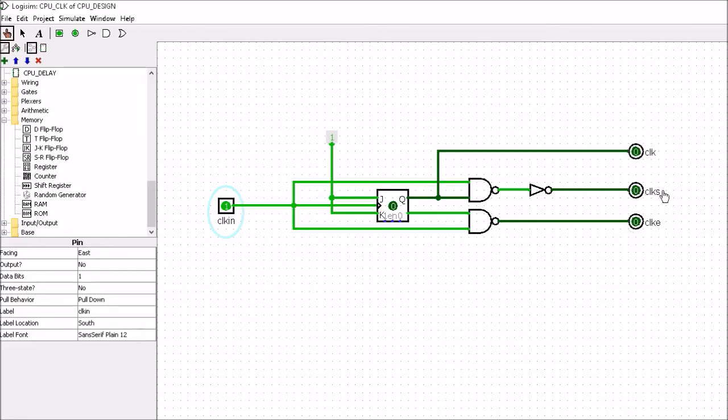So let's just look at the clock set and enable. What we want is the clock enable to go high, and then the clock set to go high, and then the clock set to go low, then the enable to go low. So watch this happening now. So we click on it and we've got the enable going high, then the set goes high, the set goes low, and then the enable goes low, and that process repeats over and over. So that's all we really want to do with the clock.